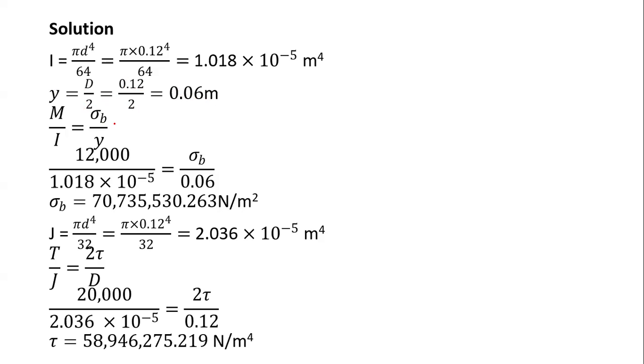So now I can apply the bending equation, the first two. Because in the bending equation, what we used to have was M over I is equal to the bending stress over Y, which is equal to, once again, E over R. Now this stress is the one we are calling the bending stress, because this is actually our bending equation.